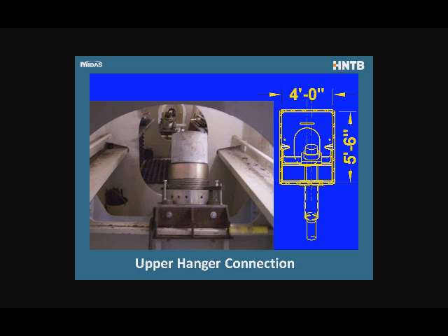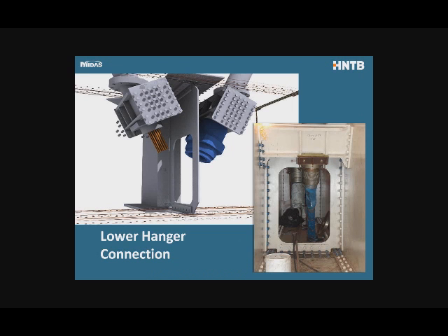But you can see in the left-hand picture, you can see the anchor beam, you can see the ring nut, and with the threads, you see the anchor head and the gray cylinder on top of the anchor head. That's the cap that protects these strand extensions from corrosion. So it's a well enclosed system. And that can be installed with very light equipment.